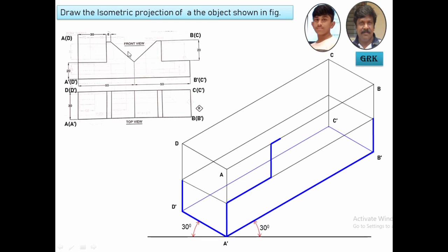Now you want to get this point which lies on the same plane. To draw this line, we are going to take the horizontal length from here to here, mark it over this imaginary plane, then you join it simply. Don't measure this line with isometric length, ISO scale. This is a non-isometric line, therefore it must not be measured. No need to measure this.